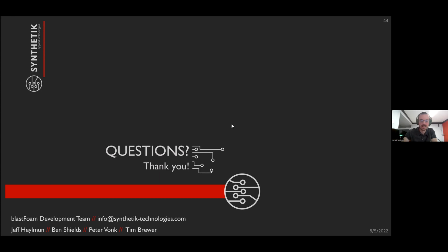So typically we'll use a little bit higher stability that way. In the event that you do happen to go slightly over 1, the simulation doesn't crash immediately. Once you get past that initial hard part, it tends to be okay. We do not have any front tracking methods. I don't know what the equation type formulations are. But it's standard TVD.